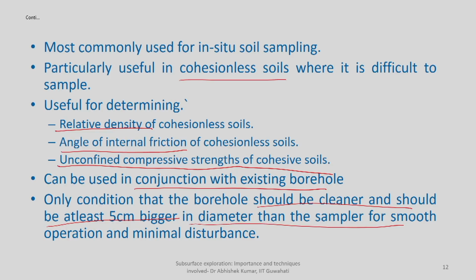So for smooth operation and for minimal disturbance, it is generally preferred that the diameter of the borehole should be at least 5 centimeter bigger in comparison to the sampler diameter.